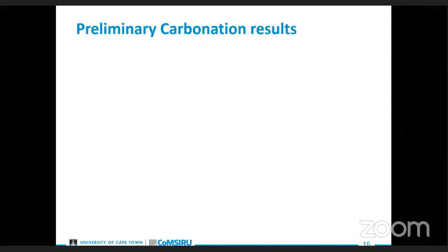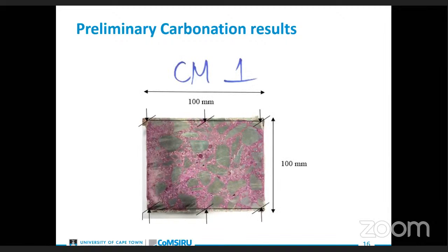In my carbonation results, after 28 days of carbon dioxide gas exposure, 10 millimeter slices were cut from the sides that allowed carbon dioxide gas through the concrete cubes, and 12 readings were recorded per concrete mix. For the accelerated carbonation test, 2 concrete cubes were used per mix and 6 readings were taken per cube. An average of 2 sides of the carbon dioxide depth on the slices was also measured to get a representative depth, as shown above.